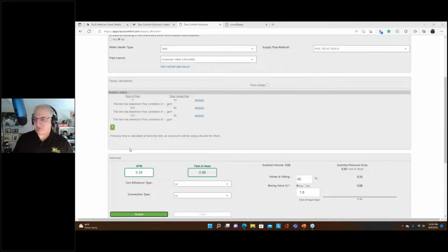What happens generally in that respect is they are either set up to run all the time or they just abandon it and say the hell with it. The other challenge, if the timer is set up properly, is that no one goes back to reprogram them when we have a switch from daylight savings to standard time, or in case there's a power outage. So there's a challenge with timers. They're simple, they're easy. And if you say I want this pump to run from 6 a.m. to 8 a.m. every day, you can do that, and that takes care of that.